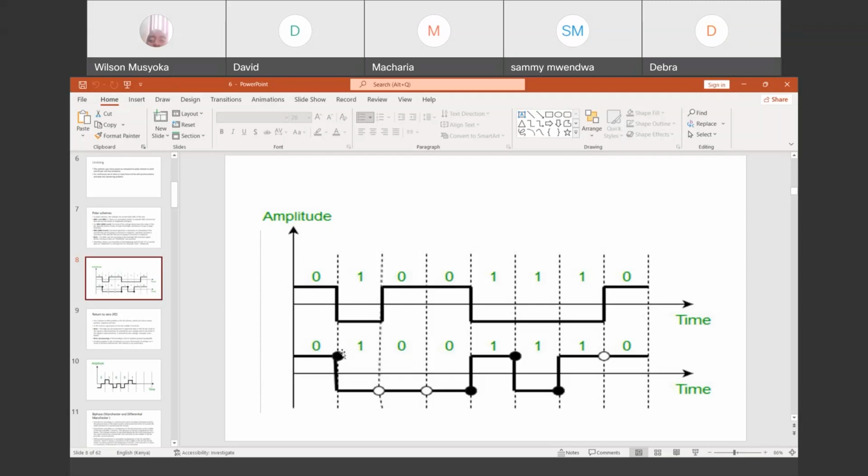When it gets another bit of data, this is bit one, right? The second bit becomes a one. That one, it is going to switch. Where there is a one, it is going to switch. So it switches to negative 5 volts because at this lower level, it is the negative voltage. Do you get it? Okay, whenever there is a zero, it is not going to switch. So when it finds a zero, no switching. It continues on that level.